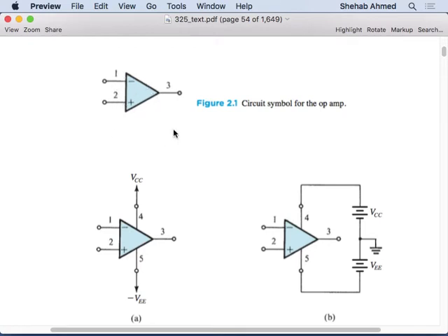As we said, the output is going to supply a voltage that is amplified, or a current that is amplified, versus the input. And where is that coming from? From supplies, external power supplies. These external power supplies can be a positive and a negative, which is called a dual rail configuration, or they can be a ground and a positive, a single rail configuration, right?